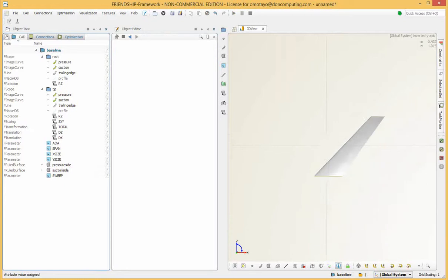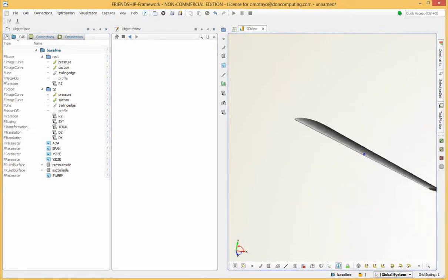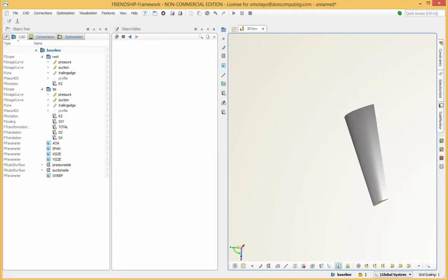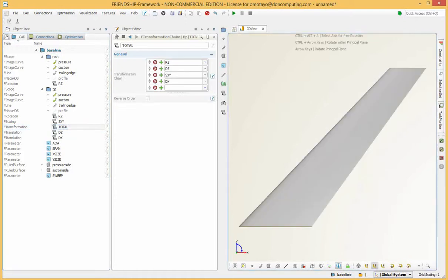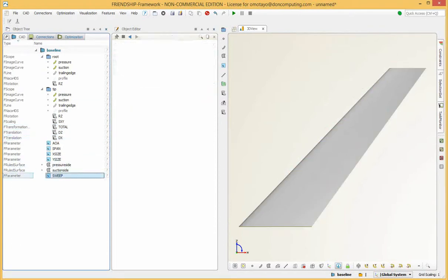This introductory tutorial outlined a quick and easy method to create a parametric model of a wing. By changing the parameter values, it is easy to modify the profile, chord, span, angle of attack, sweep, etc. Further parameters and transformation can be added to make the wing parameterization more complex, and the variations along the span can be nonlinear functions as well. The procedure utilizing functional variations will be described in advanced tutorials which will outline functional curves, curve engines, and metasurfaces.